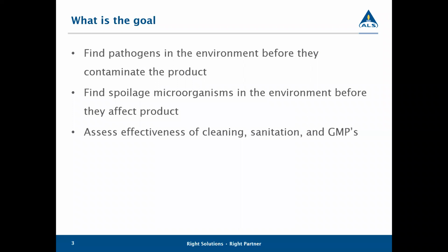So how do you achieve Salmonella and Listeria mono control? Well, there's a few steps here: thorough cleaning and sanitation, traffic control of your personnel and equipment via designated paths between high care and low care areas, being able to deliver freight and production supplies along with removing trash from the high care facilities, separation of raw and pasteurized products, air and dust control, water control, and a good sanitation program.